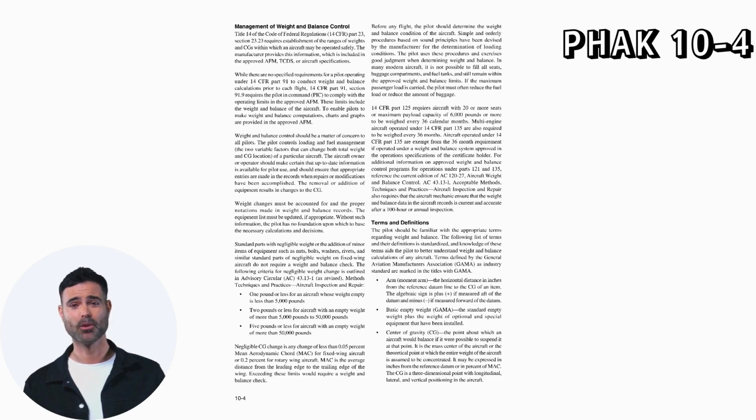1 pound or less for an aircraft whose weight empty is less than 5,000 pounds. 2 pounds or less for aircraft with an empty weight of more than 5,000 pounds to 50,000 pounds. 5 pounds or less for aircraft with an empty weight of more than 50,000 pounds. Negligible CG change is any change of less than 0.05 percent mean aerodynamic chord, MAC, for fixed-wing aircraft, or 0.2 percent for rotary-wing aircraft. MAC is the average distance from the leading edge to the trailing edge of the wing. Exceeding these limits would require a weight and balance check.